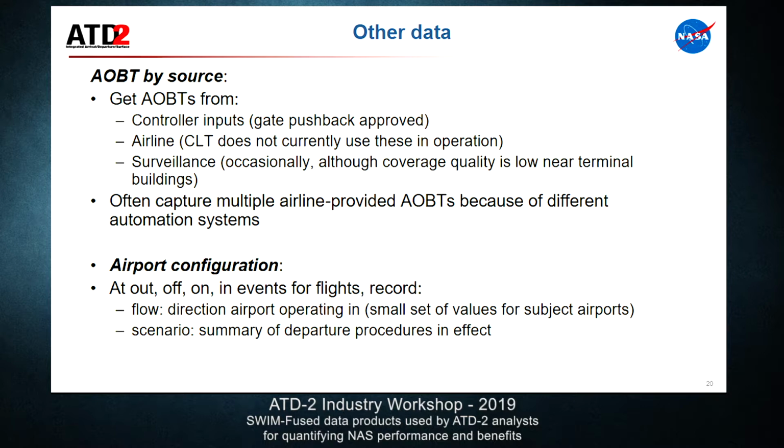Do you get SIPS data for Charlotte? We do. We don't leverage it though. So that's through the FAA STDDS feed, there are the surface movement event indicators that come through. It's a parallel stream to the surveillance that comes with ASDE-X, where the FAA systems are inferring these times as well, and we're not using those right now. But yeah, that's a whole other source that might be another 30-second difference that confuses us even further.